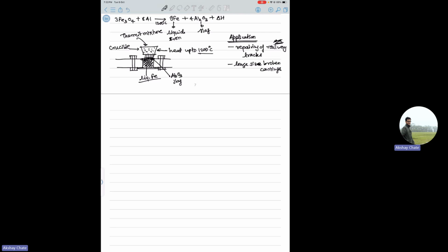Okay, so in spot welding, you cannot get leak-proof joints, and you'll have marks on your sheets, the nugget marks. Whereas in seam welding, you can have leak-proof joints, and seam welding is sometimes used in fabrication of automobile fuel tanks, radiator bodies, and mufflers in the exhaust system.